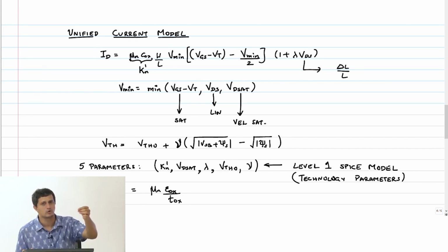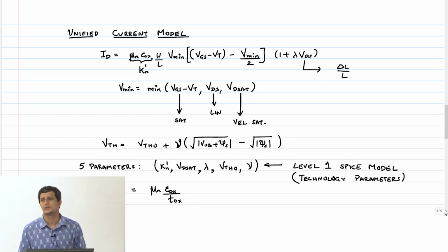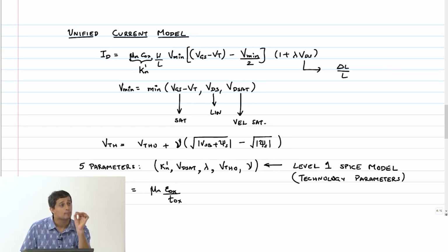In the model file yesterday you saw VDD equal to 0.8 volt. What if I apply VDD equal to 1.6 volt in that? The answers can be totally wrong. So these model files are actually specific to the application that you are doing. Here in digital design, we are fixing our L because we want maximum speed. Therefore, this VD SAT makes a lot of sense there.